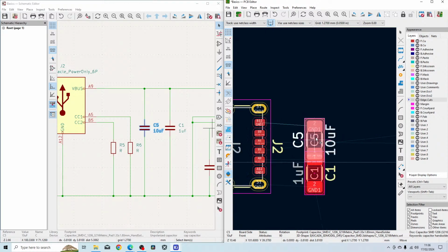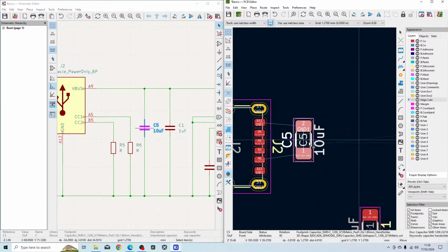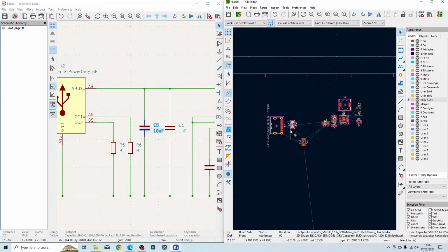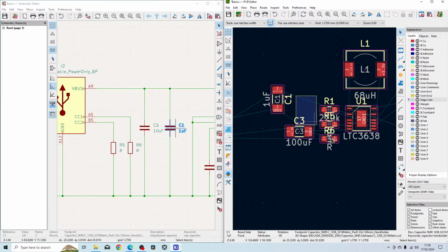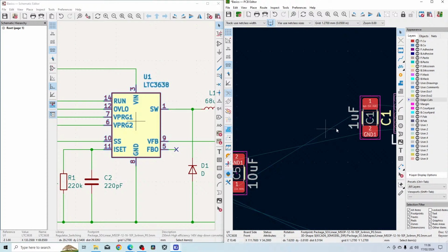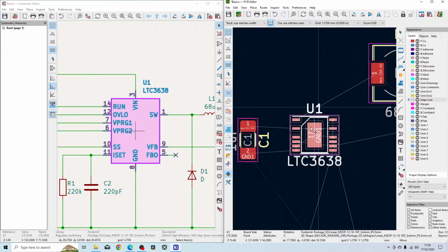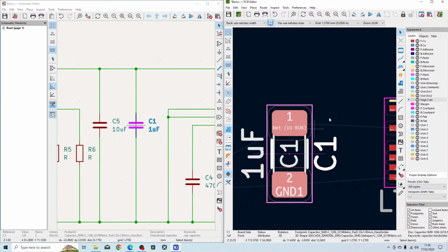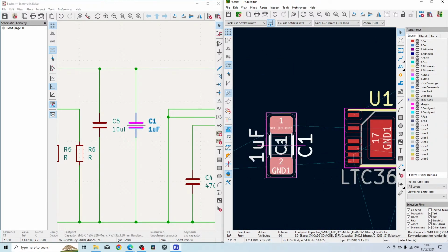So what my idea was with this was to connect the capacitor close to the inductor, unless, imagine it's a big board. You want to keep the 1 microfarad capacitor as close as possible to the chip. The reason you keep it close to the chip is to minimize track inductances, and obviously parasitic inductors in the tracks themselves can cause your voltages to dip. So if you have a short track, that is generally a good idea. So to minimize those inductances,